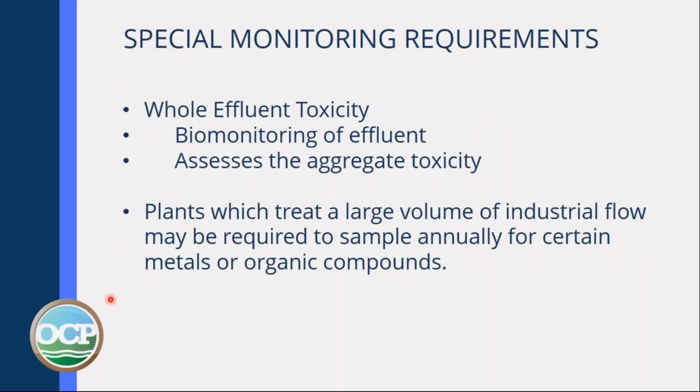Sometimes there are special monitoring requirements. There is something called whole effluent toxicity. This is where basically you take the whole effluent and you look to see the aggregate, the total effect that sample will have on essentially aquatic life.